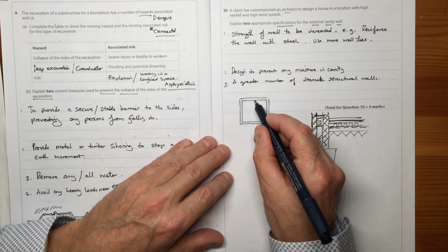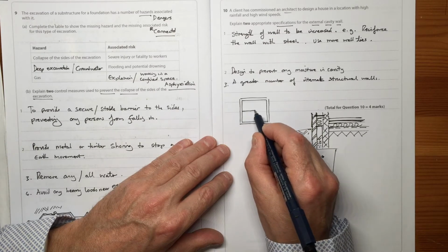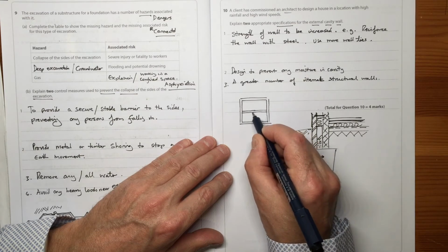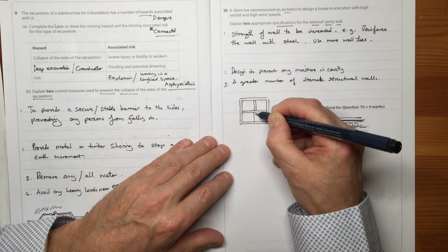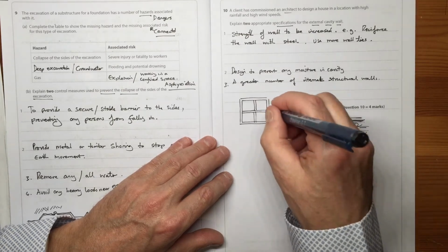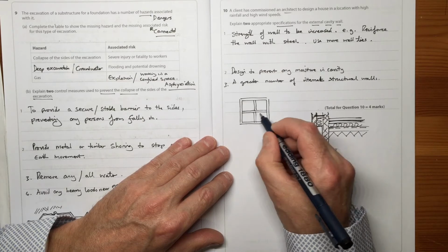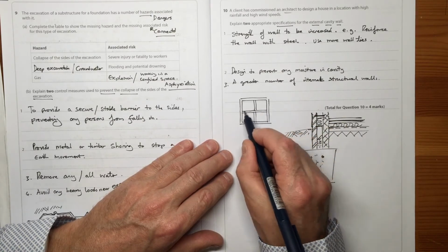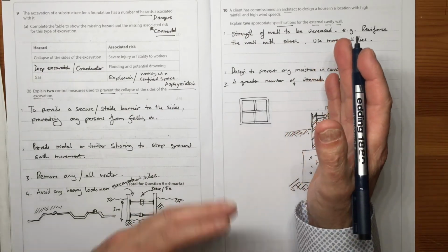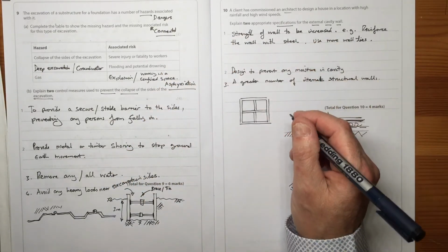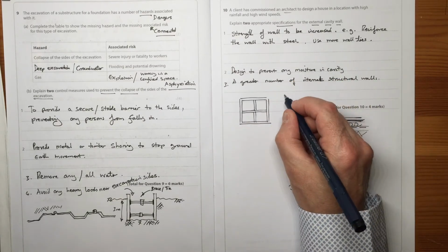Instead of perhaps having timber internal walls, you may have a structural wall that runs from side to side. Of course, you may have a door in there, and you may have another one running from this way. So the whole structure looking down is much stronger than perhaps it would be if it had timber internal walls. And these would be structural walls, concrete block or even brick. And that would give the whole place much more rigidity. That's the word. You could have deeper foundations. I'll put that down as 4.